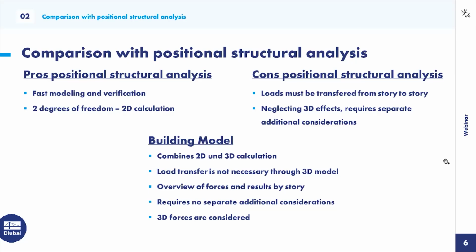Okay, another con is that this 2D calculation neglects 3D effects and, for example, some forces, let's say torsional moments, and you also need separate additional considerations or additional checks which are for the whole building.